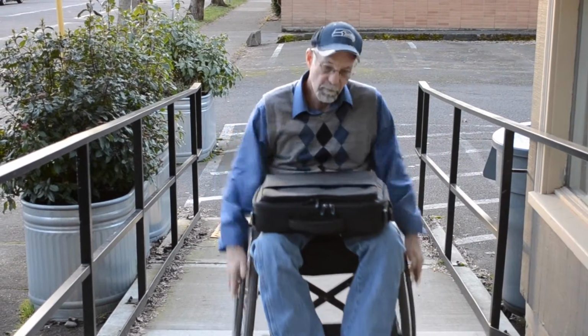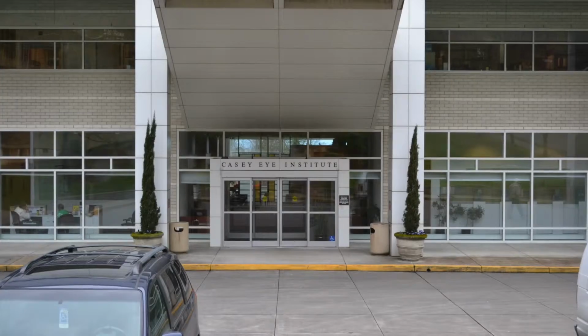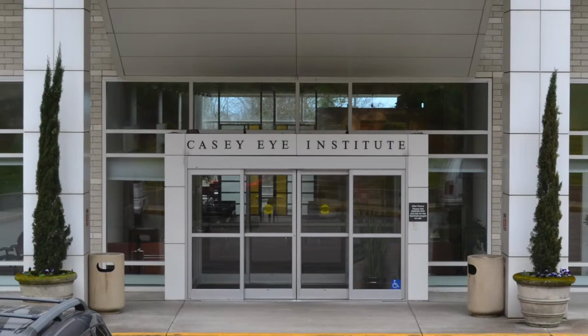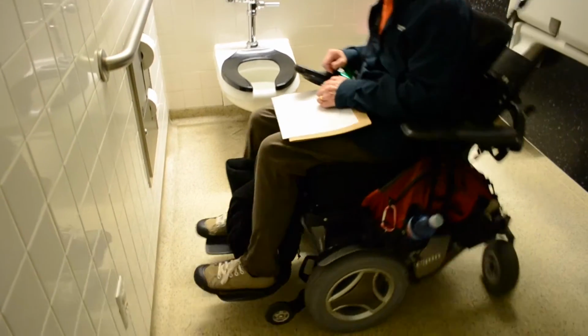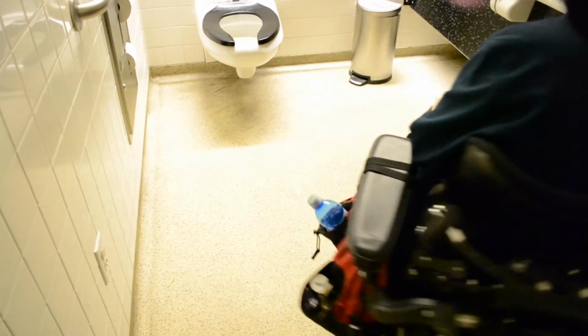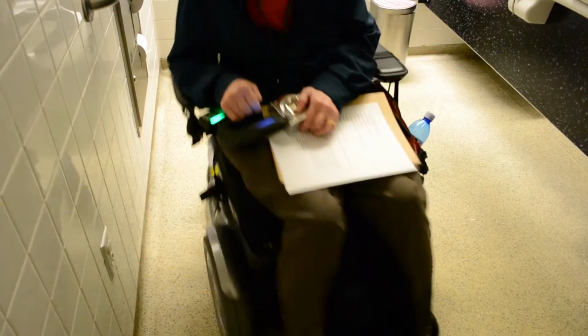However, touchpads need to be tested for the degree of force necessary for door operation. Automatic doors are ideal for large complexes with heavy pedestrian usage. Space allowance and reach ranges. The space required for a wheelchair to make a 360-degree turn is a clear space of 60 inches in diameter.